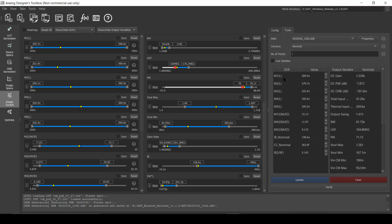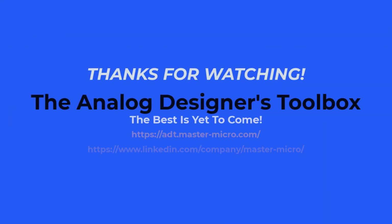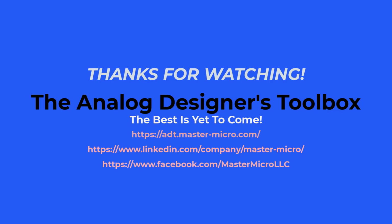We have all channel lengths, we have all GM over ID values, the current values and everything. On the right we have all the specs and widths for all devices. This was how to design a two-stage op-amp with Miller compensation in just 2 minutes with understanding everything we are going to change.